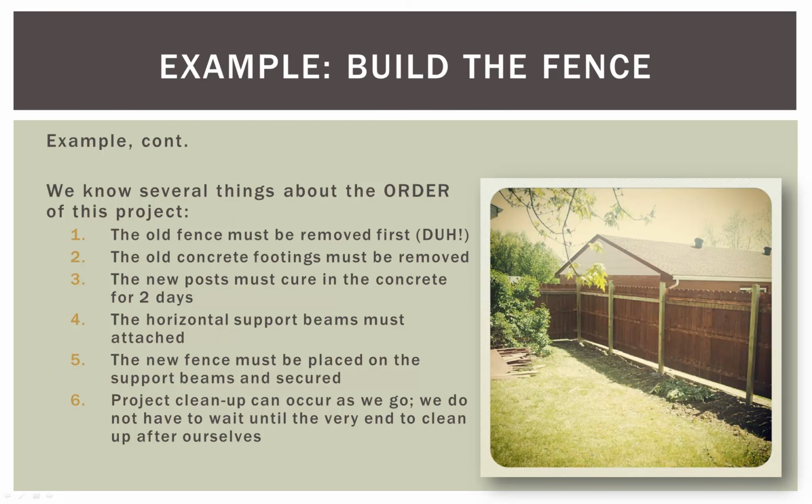The new posts had to cure for a couple of days. That way we knew our posts were securely in the ground before we hung the fence on top of it. And of course, the support beams had to be attached because if those aren't there, then the fence has nothing to hang on. And of course, the project cleanup, well, we can kind of do that as we go. So we try the best we can, but we don't have to wait until the end to do that. We could do that at any time along the way.